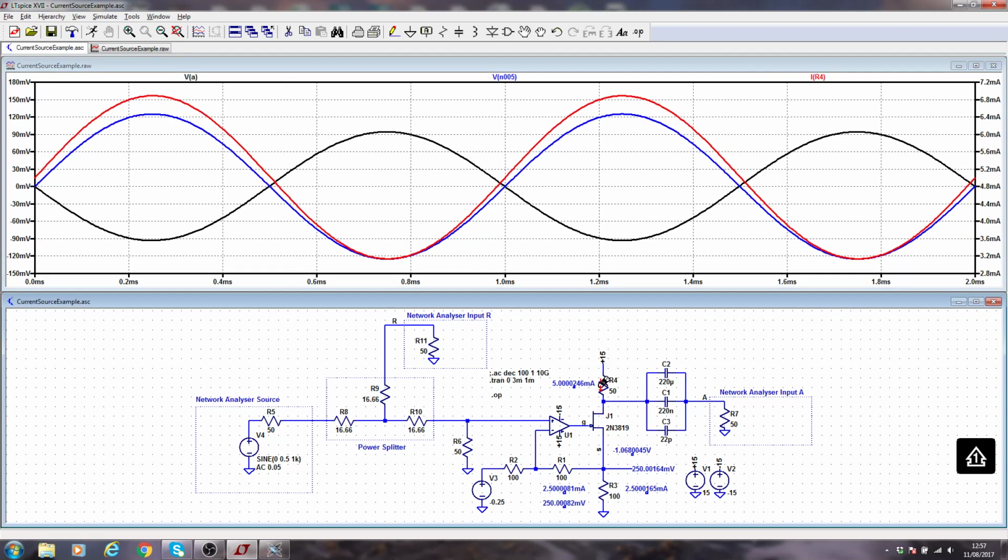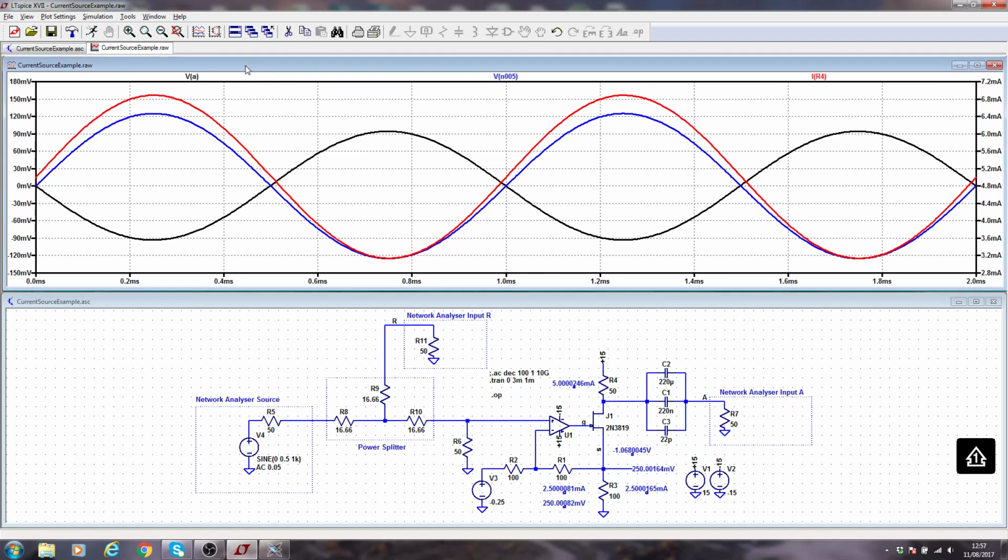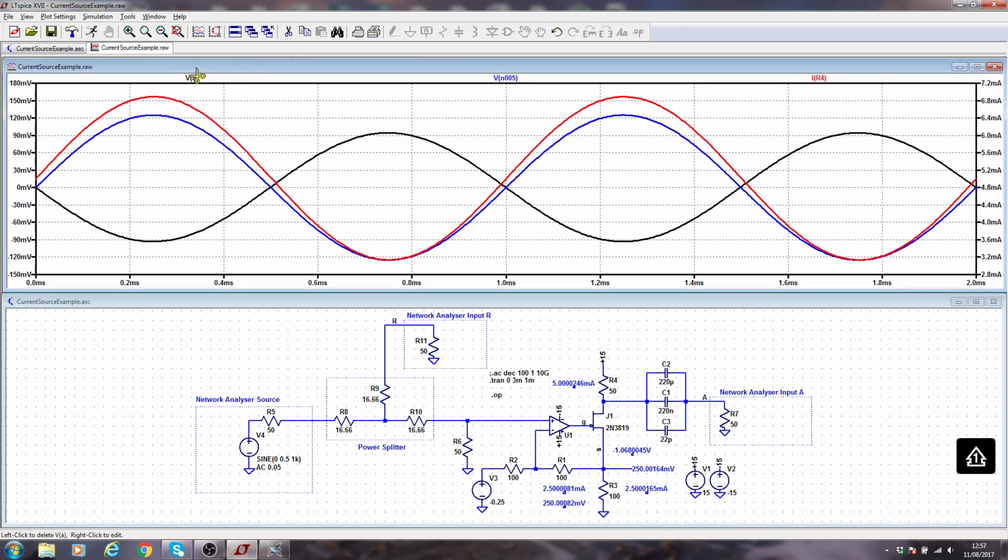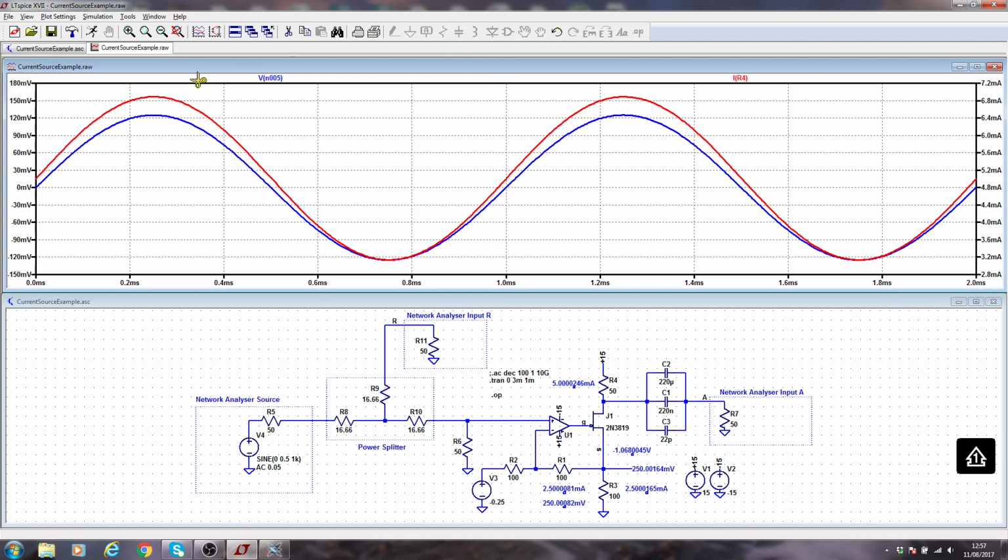If I was to do the current in R4 and I delete VA, because VA is not very significant to me now, I just click the graph pane, and then I press F5 and I get a gold pair of scissors, which is for delete. You can't delete. Oh, you can. Ah, they changed that. Cool. That used to be really annoying. Glad they changed that.